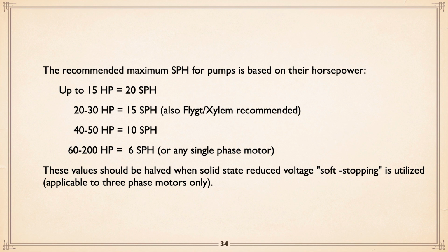The maximum for centrifugal pumps, kinetic pumps, maximum starts per hour up to a 15 horse motor, 20 starts per hour. 20 to 30 horse motor, 15 starts per hour, which is what Flygt, Xylem, recommends for everything. I think they're pushing it a bit. But anyway, on the big stuff, 40 to 50, I would reduce that to 10 starts per hour, and 60 to 200 horse, 6 starts per hour. Beyond 200 horse, boy, you're going to do some serious talking to manufacturers. Any single phase motor, I would restrict.